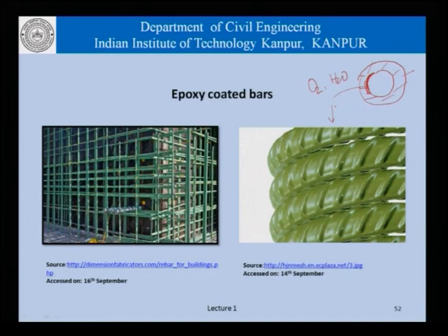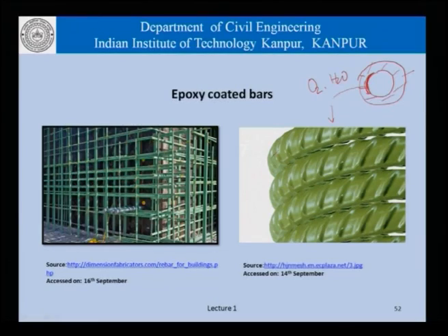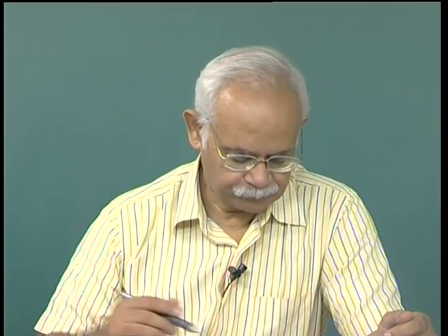This picture here shows bent epoxy coated bars, because when we bend an epoxy coated bar, we subject the outside face of the bar to tensile forces, and the coating is likely to crack. That requires that epoxy coated bars should be properly tested before they are used in a concrete construction.